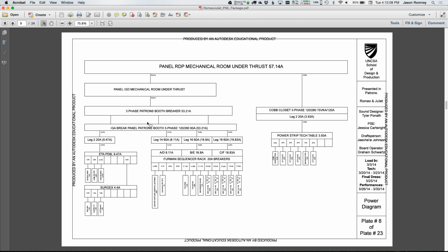Don't be scared. How do you tell, are the wall plates labeled? Like, how do you know what breaker they come from? Sometimes they'll be labeled, and if they aren't labeled, then you could put a label on it once you figure it out. We do have a little circuit sniffer in the lab. It's like a little transmitter that you plug into the receptacle at the wall, and then you go and try to find the panel you think it is, and there's a little receiver that you can sweep up and down the panel, and it'll beep when you get to the breaker that it's connected to. So that comes in handy sometimes when you're trying to chase things down, figure out where this is coming from.